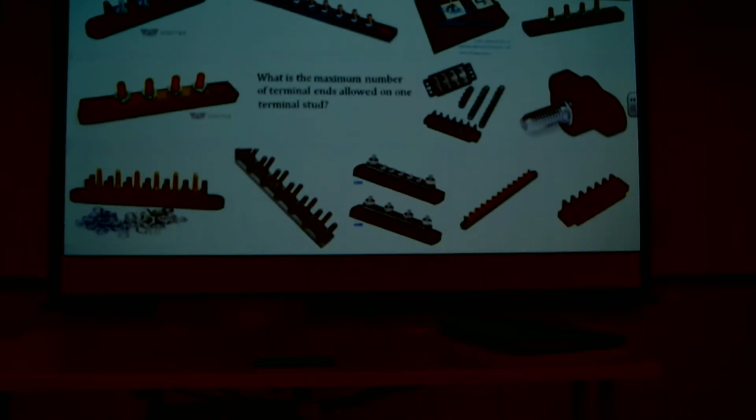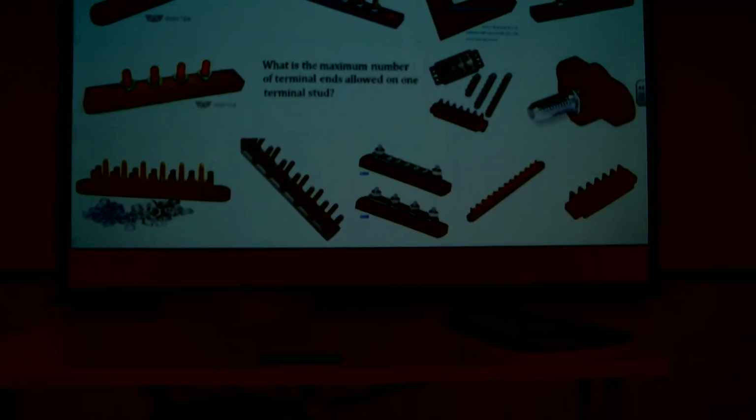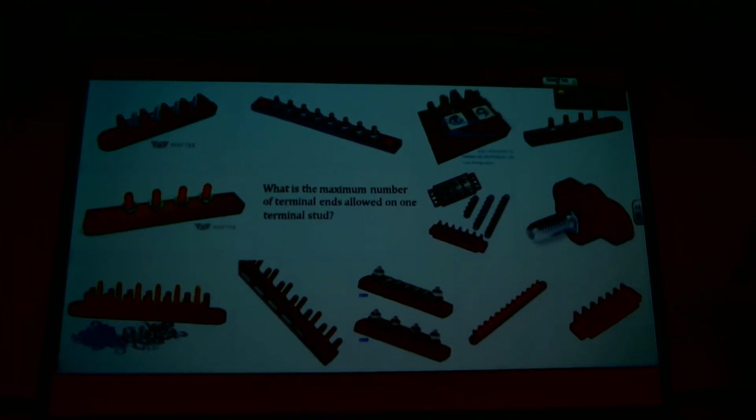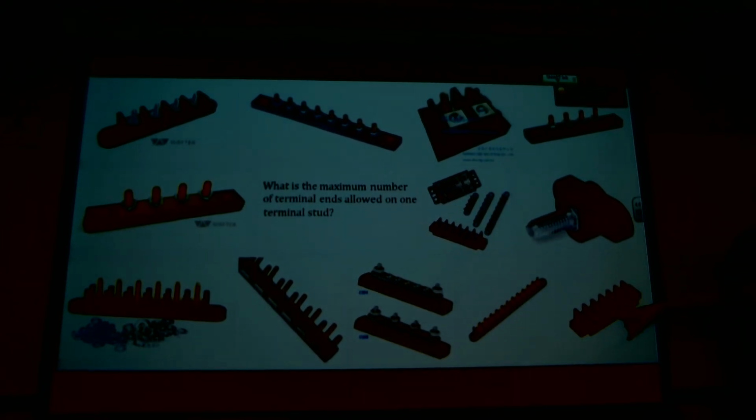So no more than 4 terminal lugs or 3 terminal lugs and a bus should be connected to any one stud. So the terminal stud should have no more than 4 connections. I did have pictures. Those are examples of terminal studs. You might just have one. This was typically one that would be hot because you can see the ridges on the top, which prevent an arc if something conductive were to fall on it.